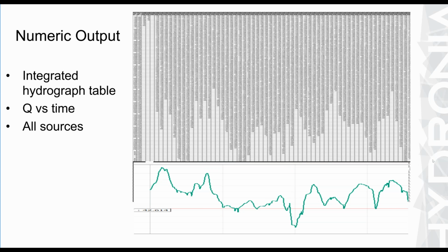And if you compare this area here, this reach, with the profile, it looks very similar. I mean, the high points correspond to spill locations that drain down more rapidly, and the lower areas show drain down much slower. So that's interesting to see that they correspond to the profile, which has a big importance in how fast the pipeline will drain.